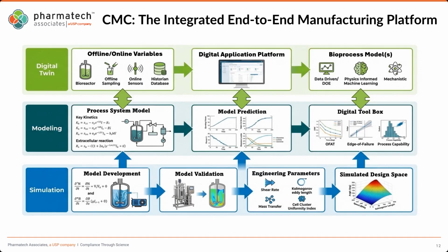The construction of the models starts from material to equipment to process. There are lots of scale-dependent properties, like mass transfer and reaction kinetics, where when you go to a larger scale there could be dead zones that give us a different reaction profile, versus some scale-independent properties like solubility or reaction rate that are not scale dependent.